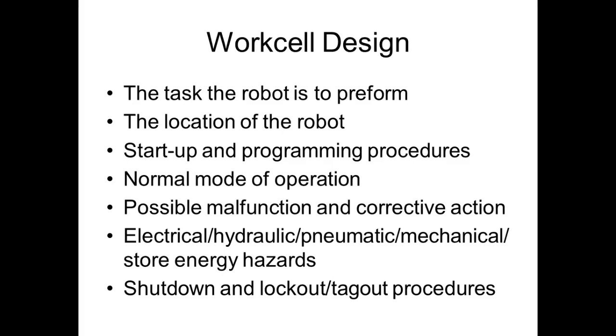So another person can remove the lock, but they've got to get permission from the person that put it on there, or they've got to exhaust everything. It's got to be a person of authority, by the way, who can remove the lock. They've got to get permission, or they've got to exhaust all means to get in touch with the person. That would be awful if I've got a plant, somebody's lock is out there, and they go home and get killed, and I can't take the lock off. But yes, other people can take that lock off, but it's got to be really extenuating circumstances to do that. And they cut it off that way.